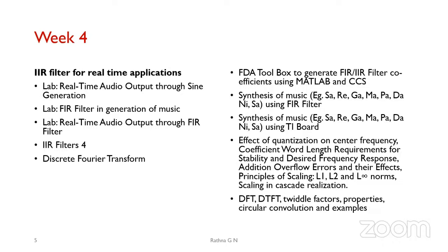As we know, DTFT is the discrete time Fourier transform. So what do we mean by that? It is discrete in time, but the frequency is continuous in DTFT. But when I'm representing this in my hardware, I cannot have any continuous part coming into the picture. Then what we want is that it should be discrete in time as well as in frequency. For that, we go for the discrete Fourier transform.